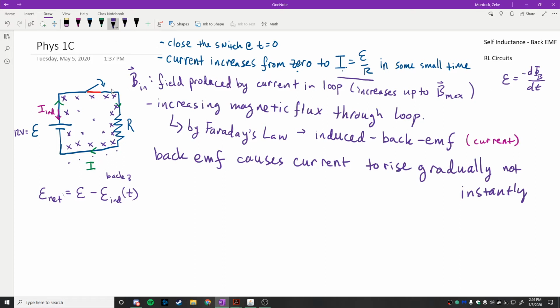And it's very important when you think about motors in particular. Motors have lots of coils of wire in them. And if you try to turn on the motor, as the motor starts to spin, there's going to be a huge amount of back EMF generated, and there's actually going to be an equilibrium that gets registered with a motor, where you have a maximum amount of output power that you can get that is dependent on how fast it's rotating inside.